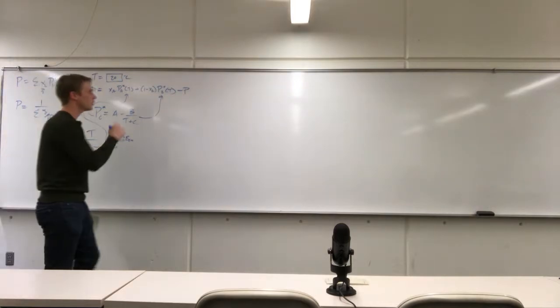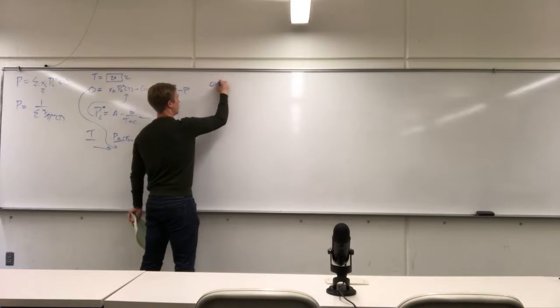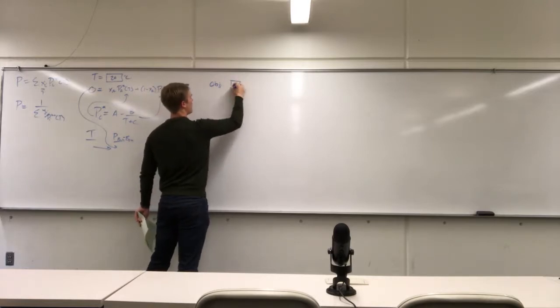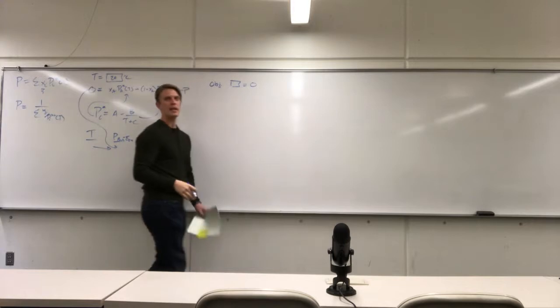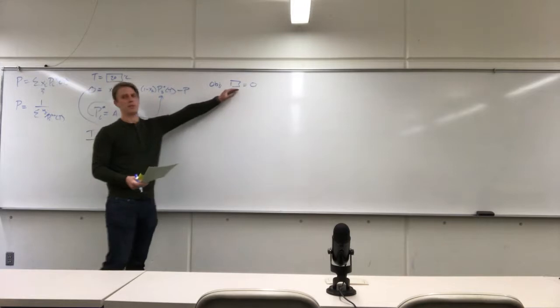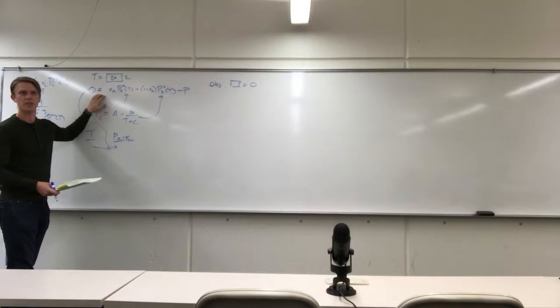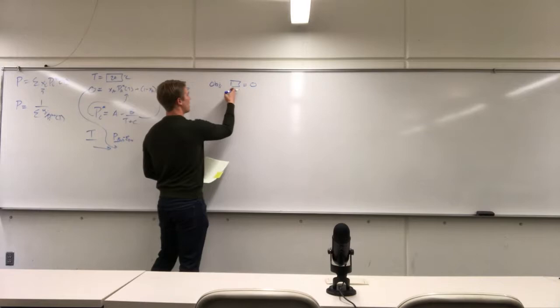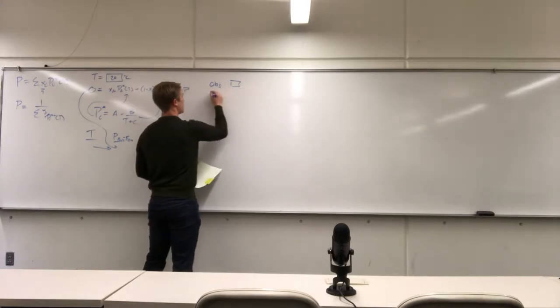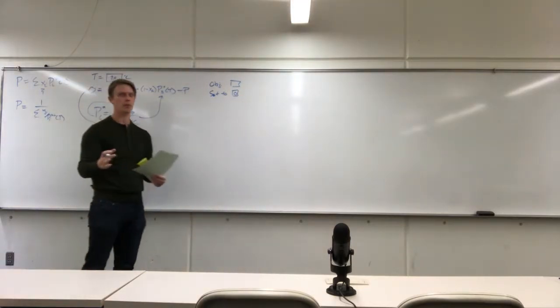So in solver, it's got this criteria where it says objective. So it's like set this cell equal to, let's say, 0. And any time you do nonlinear solving, in MATLAB, it forces you to do this: always set it equal to 0, because with any equation, it's trivial to move everything to one side of the equation. So the objective is some cell, and then in Excel it says set to, I always put 0. I want to make my life easy. I don't like remembering things.